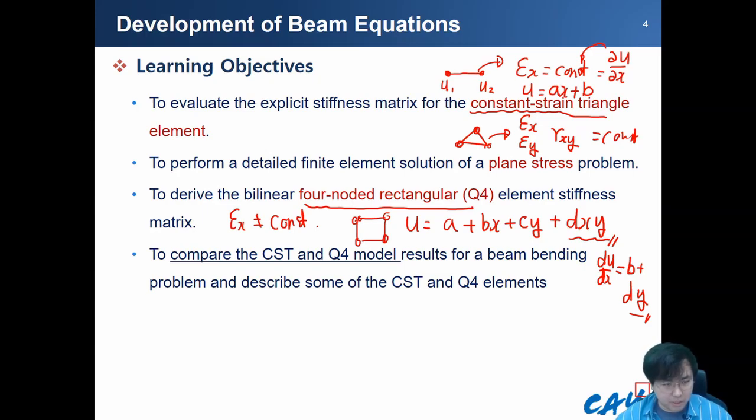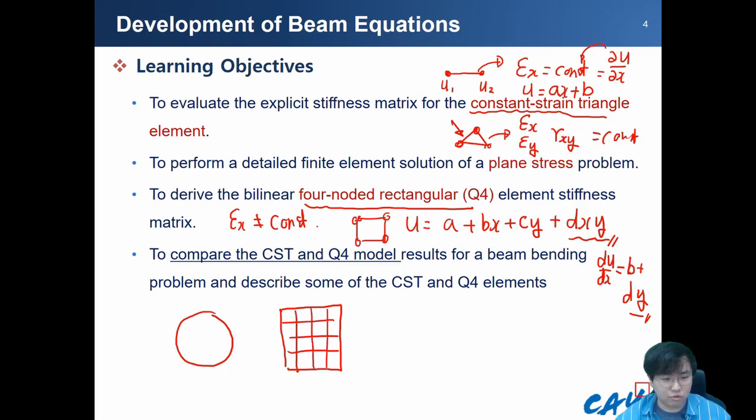An accurate strain field means that we can obtain a more accurate stress value in one element, so the Q4 element is more useful in two-dimensional analysis. However, this constant strain element is easy to use. Sometimes in two-dimensional space we have rectangular shape structures. In a rectangular shape structure, the Q4 element can be easily used.